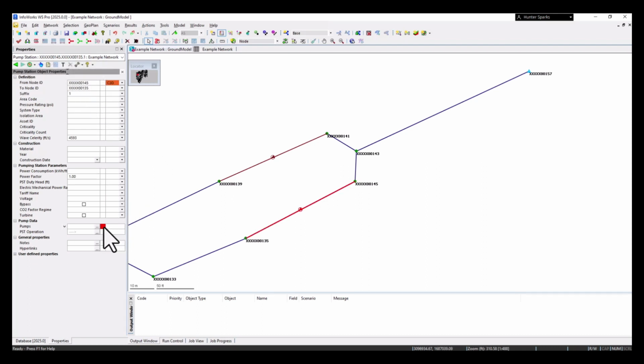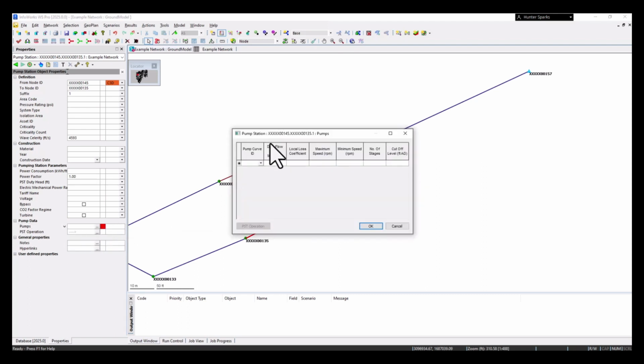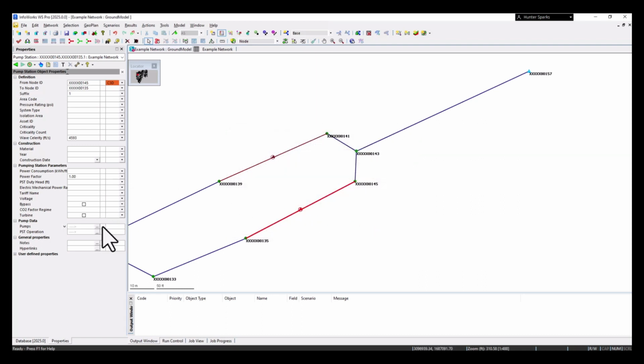And now when I open one of these, as we can see, we are now at pump station, but we're also getting a validation issue because you must assign a pump to a pump station. So we want to come in, choose that pump 120 that we just created, plug in the information that we know, so that validation went away.